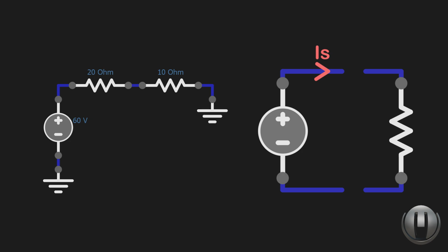We can modify the nodal analysis method, hence the name modified nodal analysis method, to add a new variable for each branch current that is unknown, and add the component mathematical model equation as an extra equation in the system. That way, the system remains exactly determined.